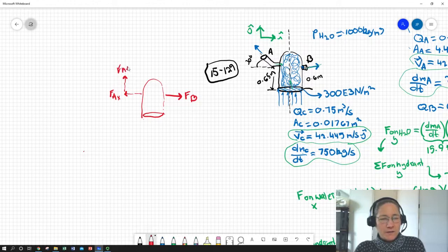force AY. If we took the moment about point C, dead center in the hydrant, the pressure forces and the force due to the momentum change of the water coming in at C aren't going to factor in because they're effectively going through point C. Basically, we can just do our R cross F, RCB, to our points of application and calculate the moments the way we would in statics.